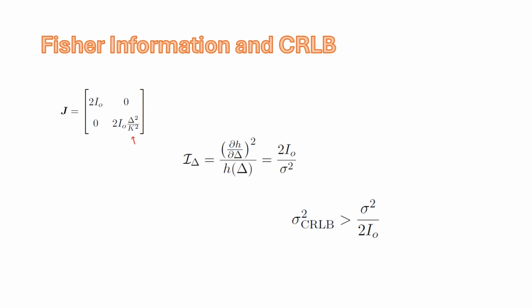When we have exactly one source, we have one mode, and we can get a null in all other measurements. With 2 sources, we can no longer get that null, and so the smallest second eigenvalue we can get is proportional to the separation delta between the 2 point sources.